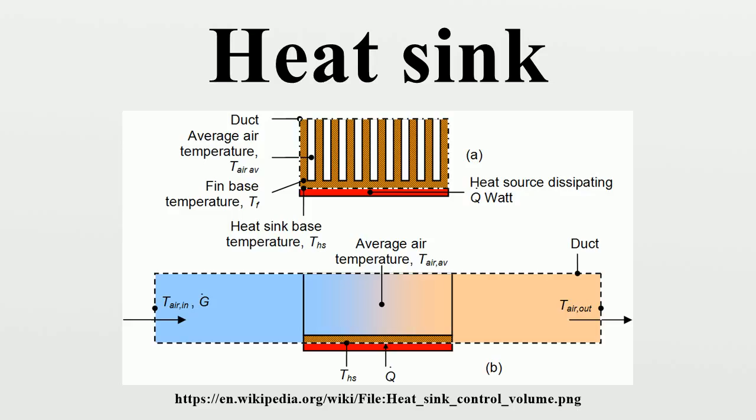Diamond is another heat sink material, and its thermal conductivity of 2000 W per meter K exceeds copper 5-fold. In contrast to metals, where heat is conducted by delocalized electrons, lattice vibrations are responsible for diamond's very high thermal conductivity. For thermal management applications, the outstanding thermal conductivity and diffusivity of diamond is essential. Nowadays, synthetic diamond is used as submounts for high-power integrated circuits and laser diodes.